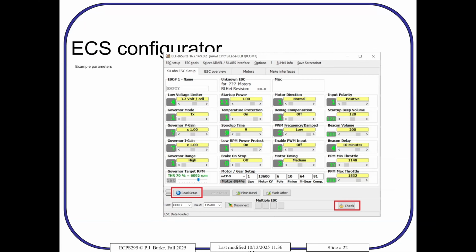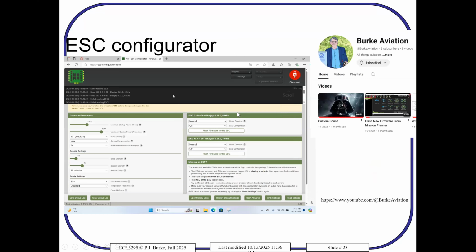So all of those you can tinker with, and you can configure that in the firmware. I'm not going to do it. I've never done it, but if you're a drone racing pilot and you really want to get every last percentage out of your motor, and you want to fine tune your ESC for your motor and your drone, you do have the ability to go in and change a lot of the parameters in the ESC.